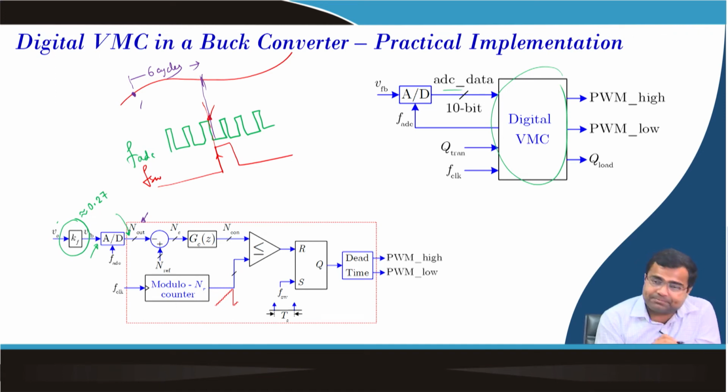Now, once it is captured, that is the number, because we have discussed the Q format, and this is in the Q1.9 signed format. So, we need to provide the n rep accordingly, because there is a scaling factor, so that it acts like a reference voltage V reference in the digital command, that is why it is n rep. And then the n error goes to the controller.